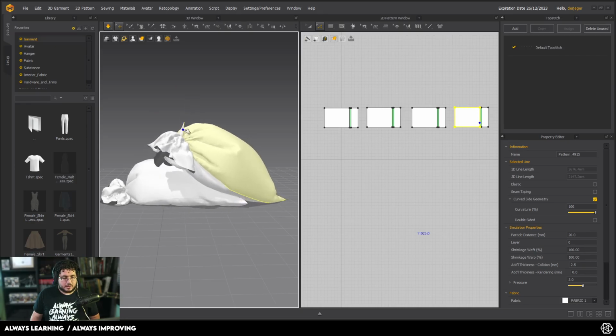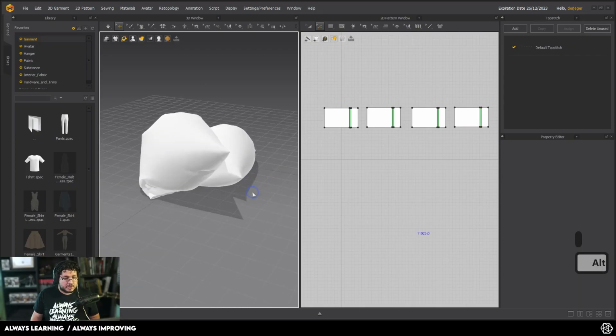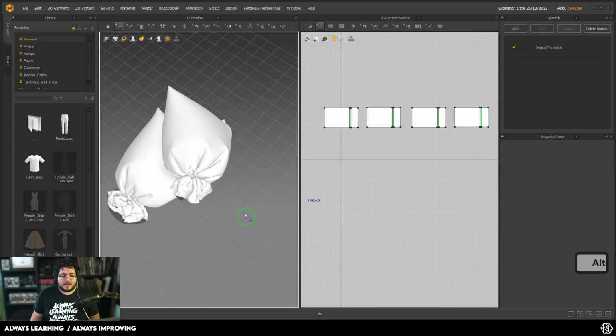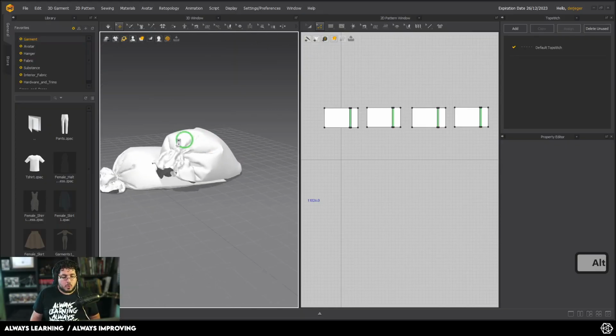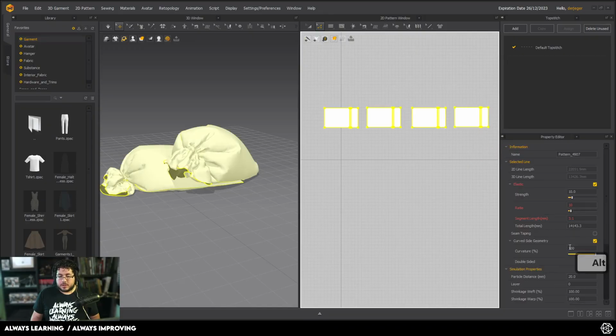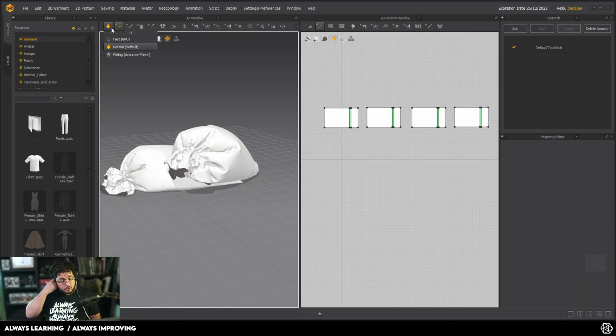Or again, at any point, you just find something that you like, let's say right around there, just press the spacebar. And if you press the spacebar, the simulation stops. And as long as you retopologize from this point, no one's going to know that this thing's about to fall, right? So yeah, the final thing that we can do here is, of course, grab every single element right here and reduce its simulation properties to something like, I don't know, a 5, which is going to be quite low. We let the simulation run a little bit more.